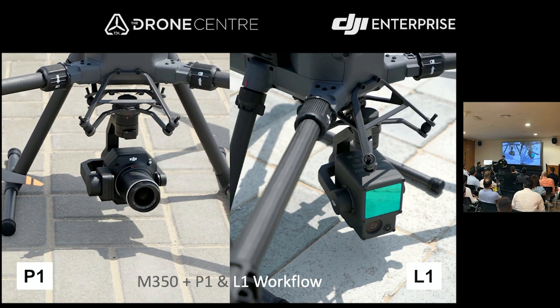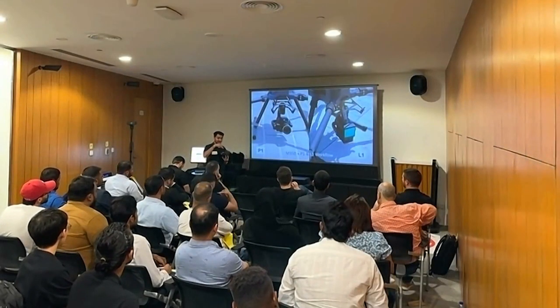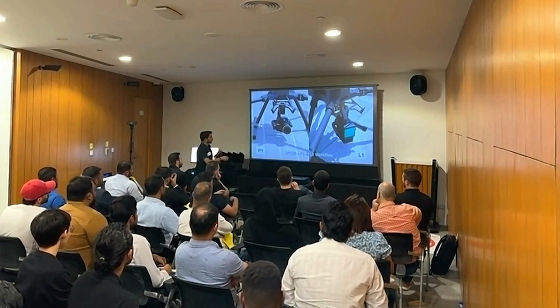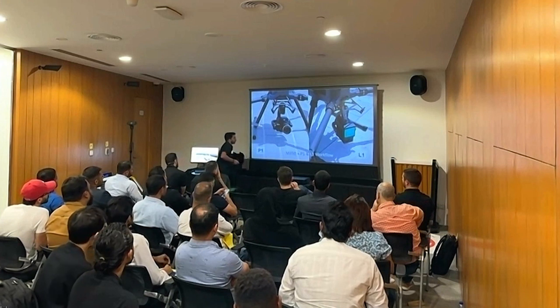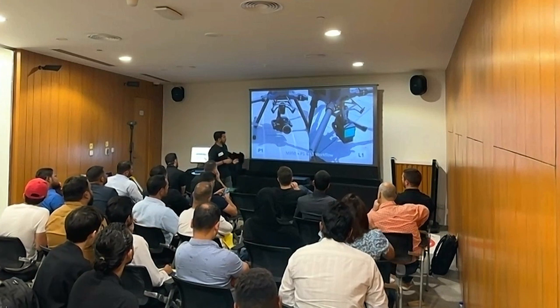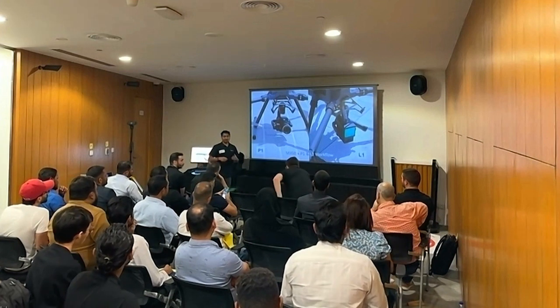I know there is not much vegetation in this region, but probably we consider Turkey. So there is a lot of vegetation, Turkey and India. So you want to penetrate deep underneath. So in that case, the LiDAR sensor is more beneficial to use, because with the P1, you cannot expect that accurate result in vegetation. So with the P1, you are getting a normal full frame sensor, as I told, 45 megapixel full frame sensor, and you have an ability to change this.